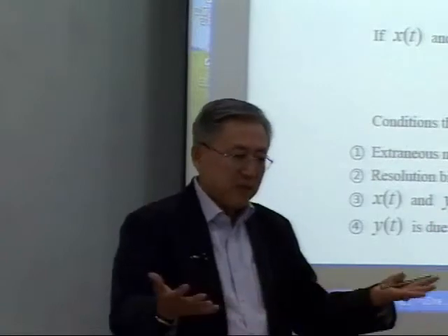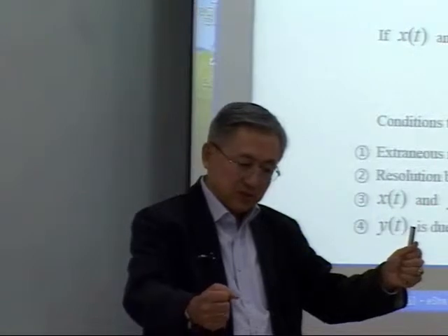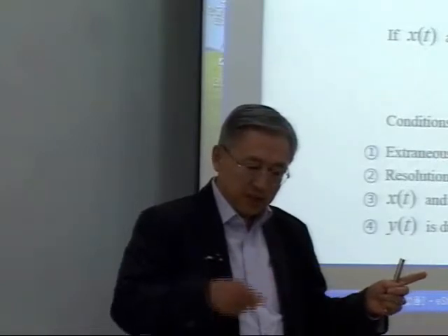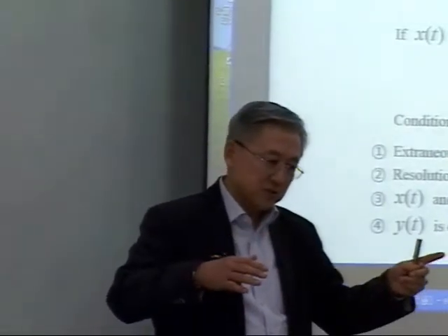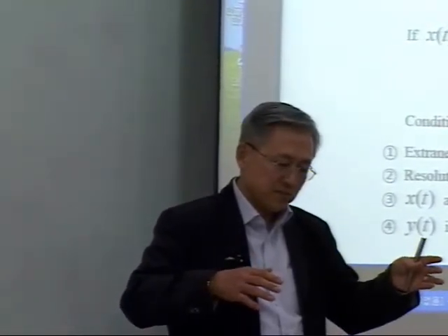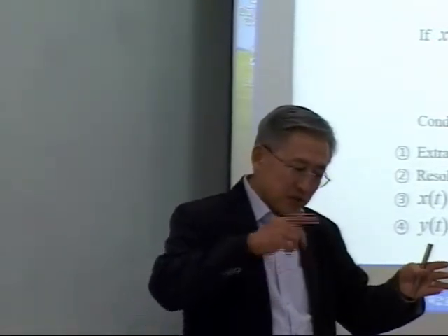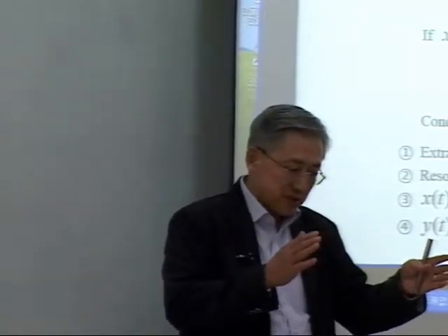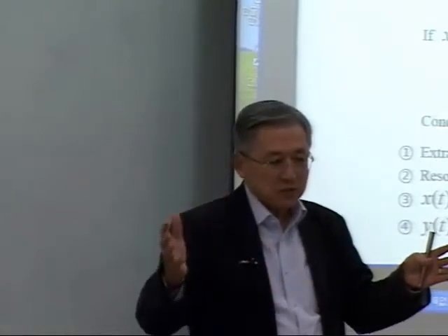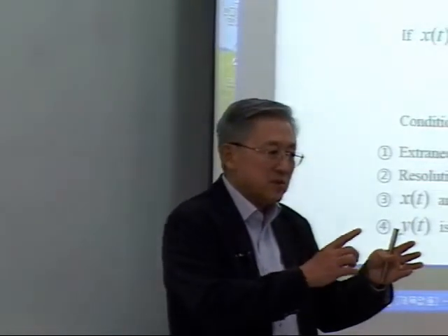I have a plate, I have a shaker, I have a transducer mounted to take a measurement. Then when you apply the sinusoidal forcing function, it will excite the plate by the shaker. As you change the frequency for the sinusoidal function, as it sweeps the frequency range, let's say from near zero to some destination frequency, it will hit the resonance, right?